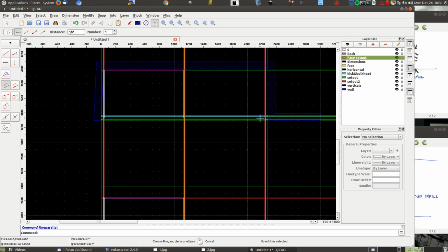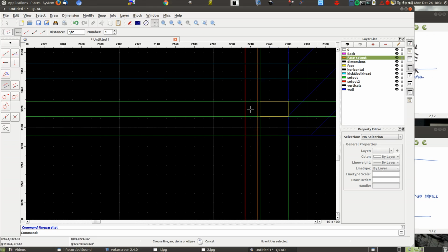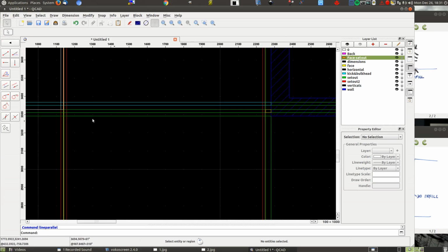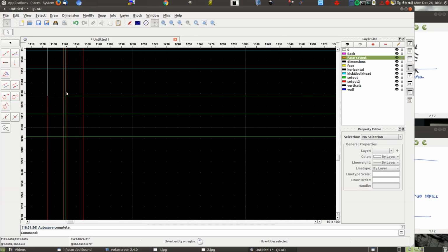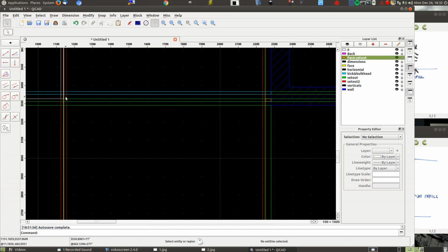So that's another thing that's quite interesting and quite important to keep track of: what clearances you have on the doors. You can't just divide the cabinet by 2. You have to be aware of the clearances and how they interact. Here we've got a full clearance in the cabinet, and there we've got a half clearance. So to know the dimension that we ought to make the door, we have to include the